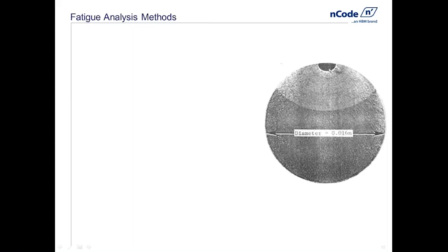And the interesting thing is, if we look through this failure surface, we can see that the surface just looks different. You could almost look at this as a map. The landscape has changed. Something looks different here than there. And this is a great way to illustrate what we mean by crack initiation and crack growth. We can see that the crack started here. For some reason, the stress was highest here, or there was some type of a defect, a material flaw in this region that caused stress to be magnified.